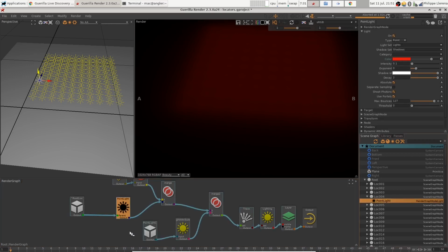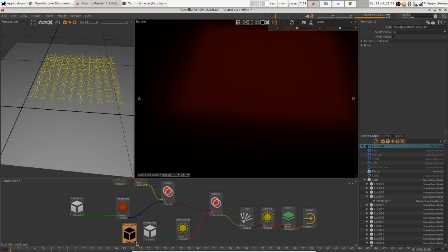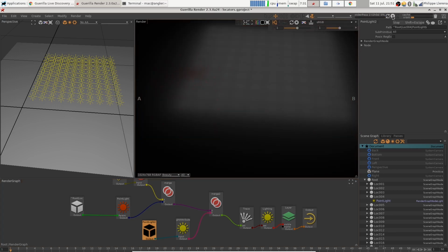So I will go for something more precise, and I'm going to get not only all the elements ending with my point light, which is going to be on the instance, but I want to choose one light specifically, which is light number 4, and only light number 4 is going to turn red. So I can play with the Lua pattern. That's something I love, and I say all the lights ending with 4 are going to be affected by the red color, and that's my case.